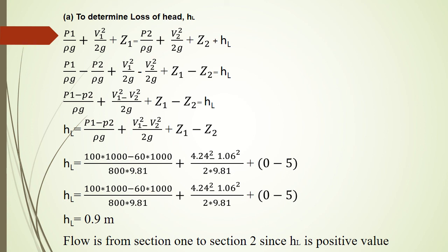Keeping all these basics in mind, I can solve any kind of problem. Here one should remember that the continuity equation is used to calculate the velocity, so that you can make use of these velocity terms in Bernoulli's equation. This is the first thing you should remember.